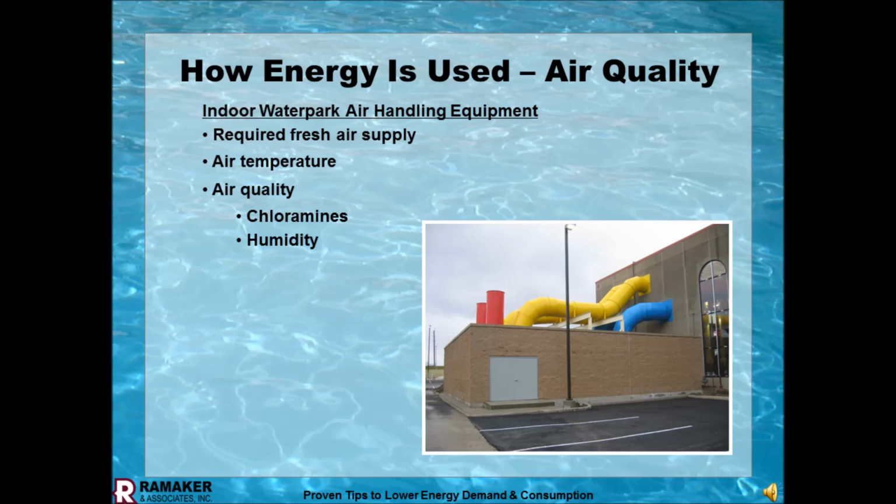The reason we're moving the air so much is it's really working on the air quality and working for the chloramines. In the hotel scenario, the small hotel where you walk in the lobby and they have a pool, I really hate that. It shouldn't have that smell. Air handlers, about 4 to 6 turnovers per hour is what it was shaken out to be.